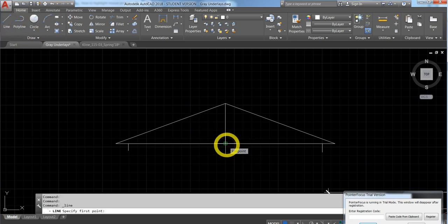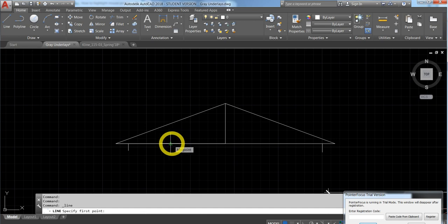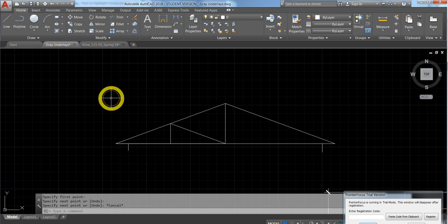So again, our truss is built with these different chords. So now I'm going to draw a line from here to here. And this will allow me to find the midpoint of this chord. So I'm going to draw this up. Perfect. And then from here, I'm just going to go ahead and finish my truss. And that's really it. So again, these are just each one of these members, and we're not even going to identify what it is, but let's just say it's a 2x4. So we've got a 2x4 running point to point, another 2x4 going vertical to support this, as well as over here. And these again are all prefabricated and then just shipped to site.